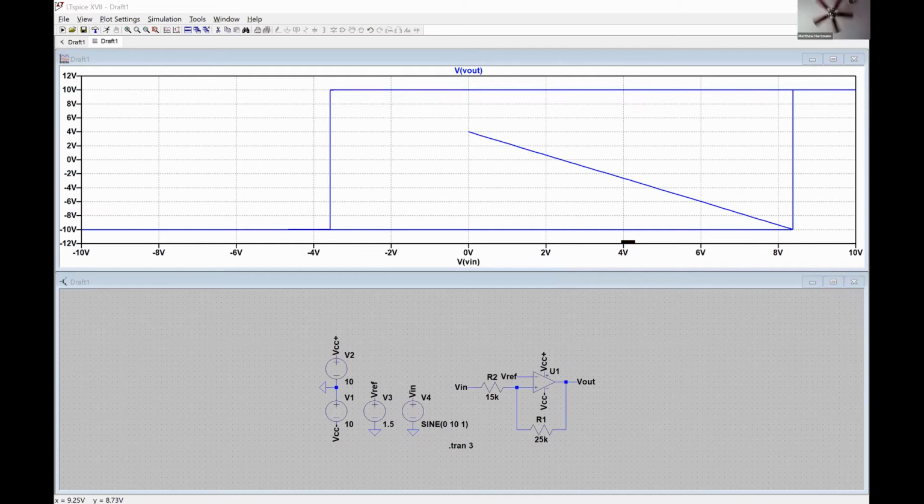Okay, so this is a hysteresis loop, which you may not be familiar with yet. Can you see my cursor? Yes. Okay, so what's happening here is this voltage is effectively at its low value until it hits, I guess, something around 8.4 volts, at which point it swings up to positive saturation, and then it's going to stay at positive saturation until it reaches 10 volts.